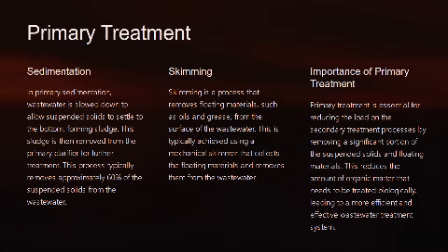So 2 things to note. The first one has to do with sedimentation. And what you do during this stage is that you slow down the water. The idea is to make sure that all the solids that you could not screen out settle to the bottom. When they settle to the bottom, they form a sludge. So what you can then do is scoop the sludge out, and remove the sludge from the water.